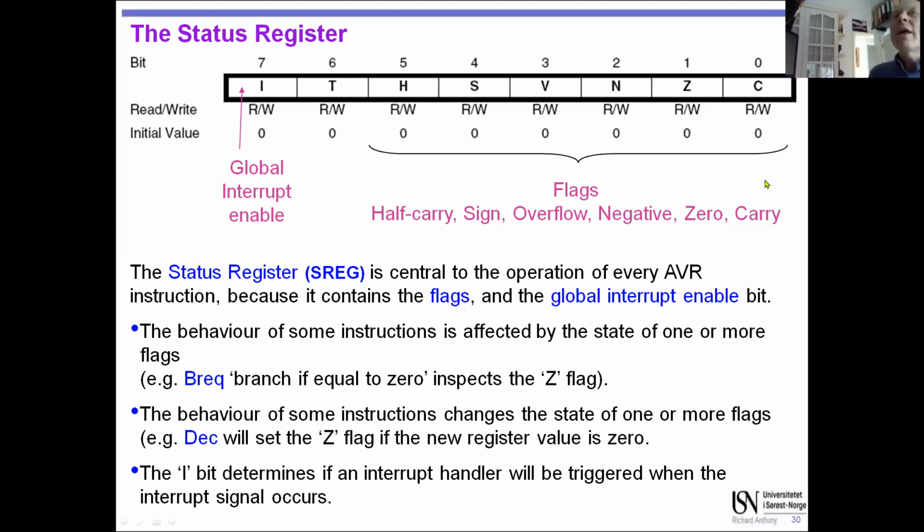So for example, suppose you subtract a number from another number and the end result is negative. This negative flag will be set. So you know it's negative, because otherwise you might think it's positive, because again it depends if you're using signed or unsigned arithmetic. You won't necessarily automatically know, or the compiler, if it's a C program that has to interpret this, wouldn't automatically know that the result was a negative number. So this flag says, oh, the result of that was negative,